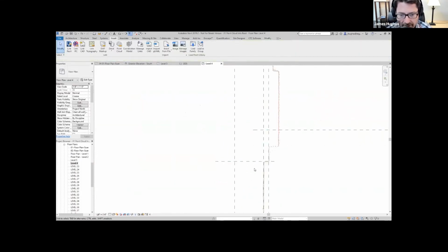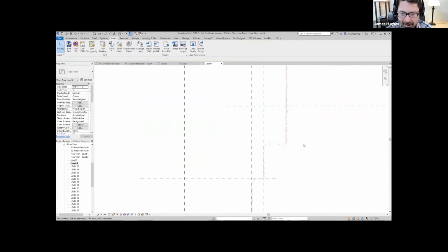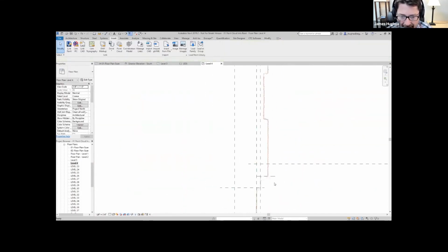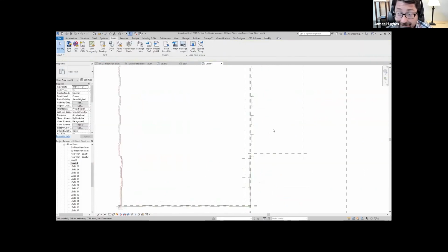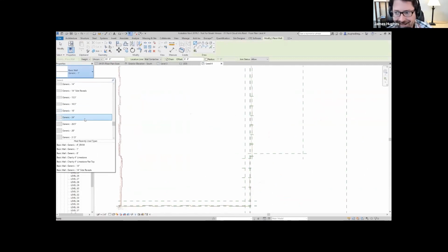At this point, we're just taking some careful measurements and finding it was 4 feet typical there. Here we've got an 8-inch limestone offset. Or, I'm sorry, 1 foot back here. You can modify that and use nice round numbers for a measured element. You don't have to do it that way. If you want to have fractional nonsense numbers, you can do that too.